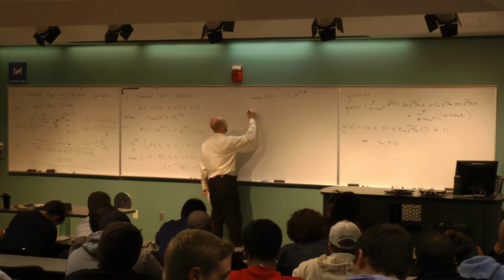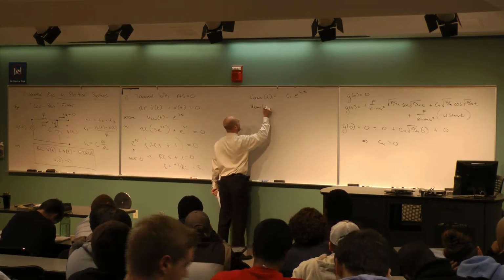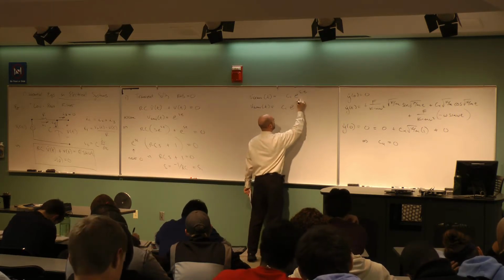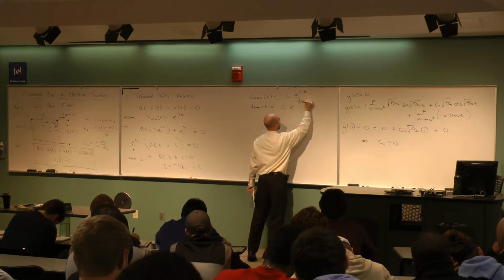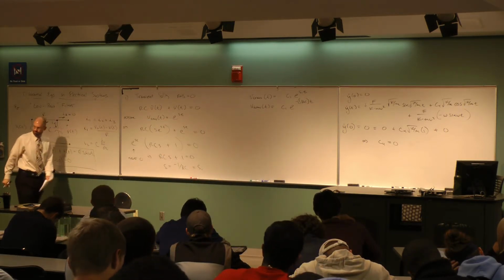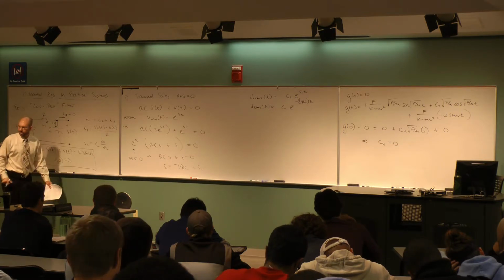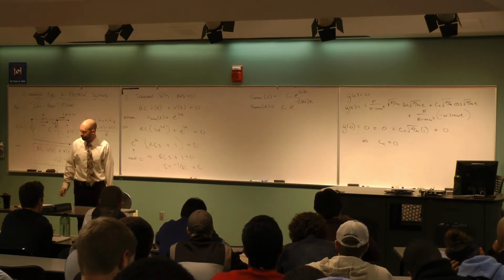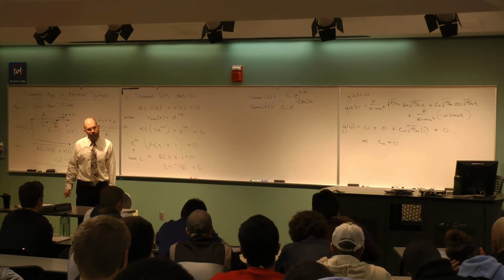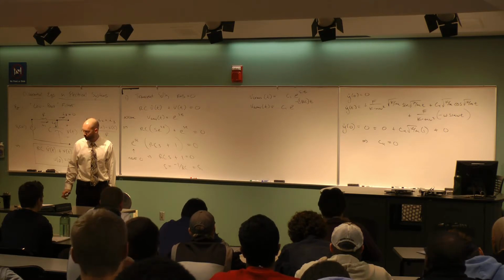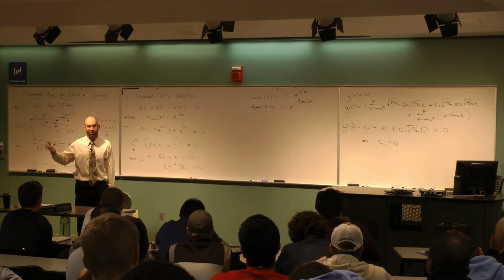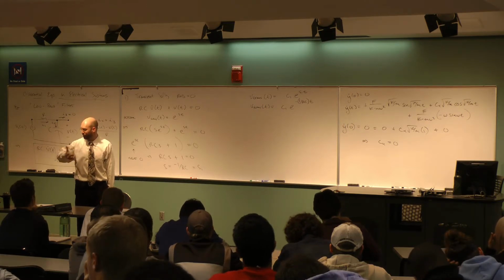Okay, and so let's go ahead and plug the number in. V transient of t is equal to C1, some unknown constant, e to the minus 1 over RC, okay, times time. By the way, no matter what the C1 is, how would you describe that physically? What's going to happen there? It's a decaying exponential. Okay, there's a pattern to these differential equations, right?